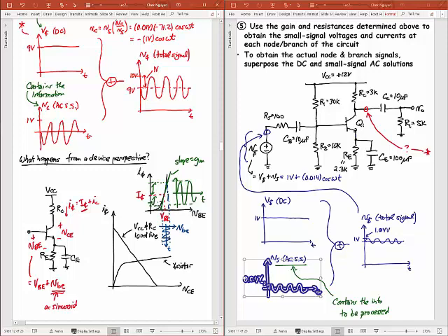Okay? So that's the output current, but what we're really getting out of this is an output voltage, right? It's not an output current. So now I've got to go on this axis here and look at that change in collector current. And so again, on this, I have to find my bias point, and maybe my bias point's right here. I don't have to find it. It's where the load line intersects the line for the transistor here. And this line for the transistor is for one case. This is for the bias point of the transistor.